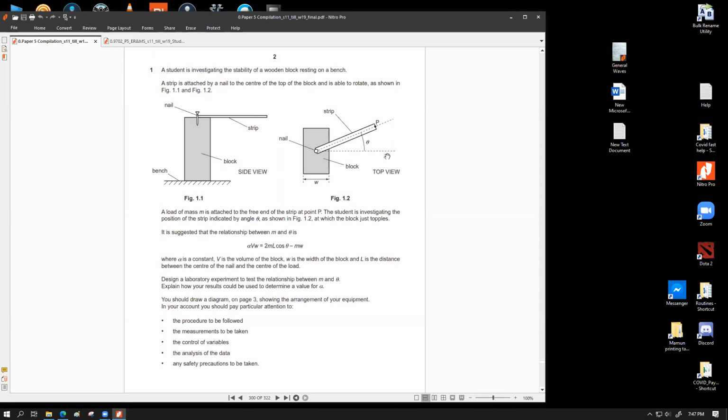Measuring angles with trigonometric values always gives better precision compared to the protractor, because typical protractors are graded in 1 degree, so you have an uncertainty of plus or minus 1 degree. Whereas with the trigonometric method, you measure the lengths and find the ratio from the mathematical output. That gives you a fraction of values, which is more dependable. So we can find the exact value of theta for which the block topples over. This is possible to achieve, number one.